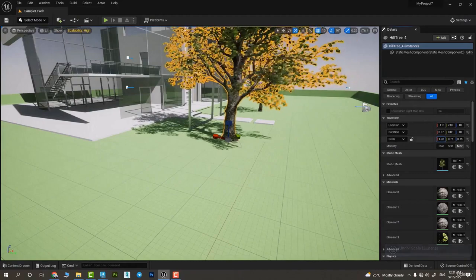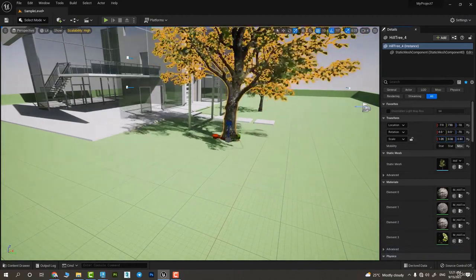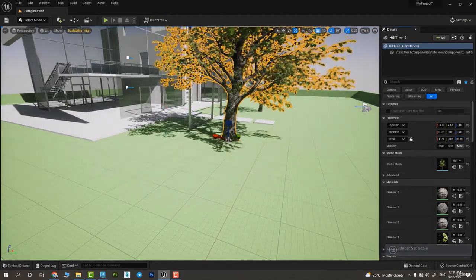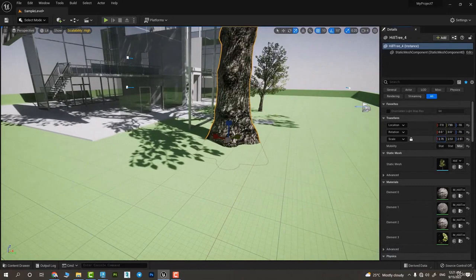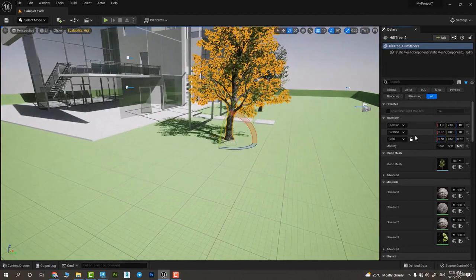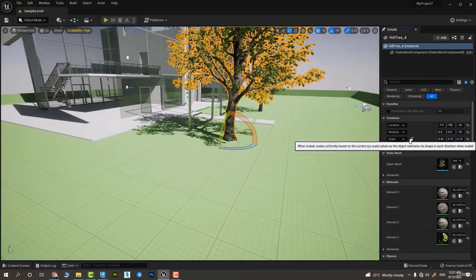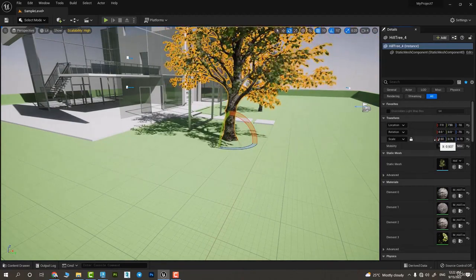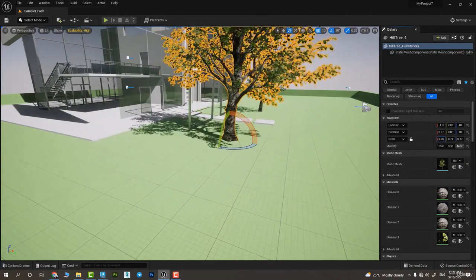And again, like the previous controls, we can just use the scale numbers and scale our object to our desire with these numbers. Okay, so again, a very useful tool. We can just manipulate these numbers, put in certain values that we have received before, and scale our objects. And you can use this lock for keeping proportions. So if you unlock it, you can just change the scale on one axis. If you lock it, when you change the scale, the proportion is going to be kept intact.